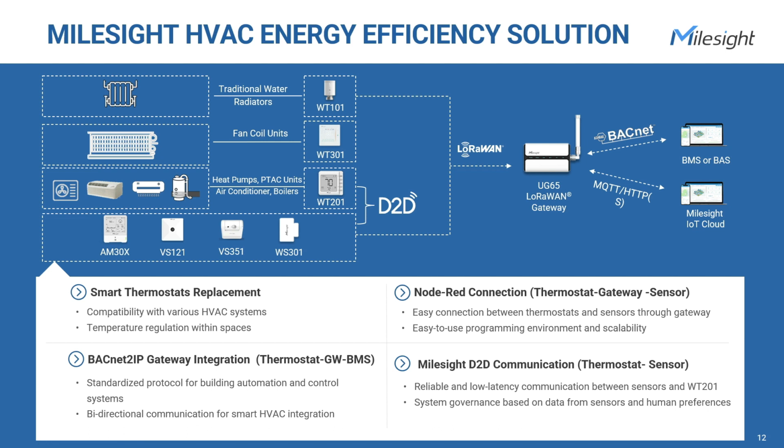Since the thermostat is connected to the internet, you can easily communicate with it using any other internet-connected device to ensure a dedicated data connection without interference. This UG65 gateway synchronizes the control data in the cloud. This means you can access, monitor, and control your smart thermostat through software like the Milesight IoT cloud platform. The smart thermostat approach is an affordable way to gain remote access to your facilities when you are away. If greater insights are needed, bolt-on functionality is available in the form of air quality sensors, occupancy detection sensors, people counters, and more.